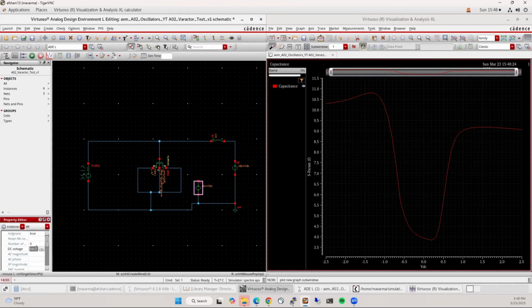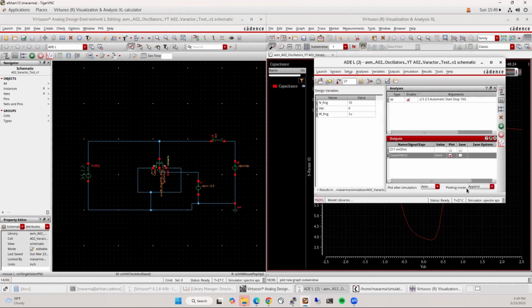And this needs to be connected to minus VDD, so minus 2.5. And that connects to the body, right? So this should get rid of the accumulation mode, and you end up with just inversion. So let's test it.